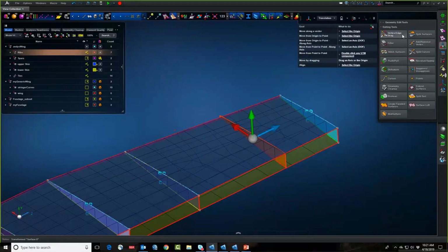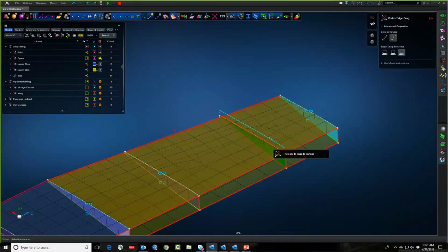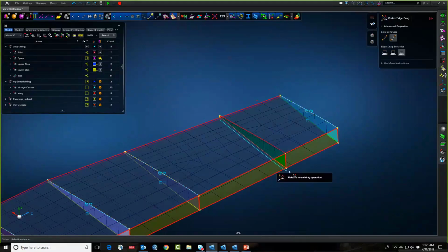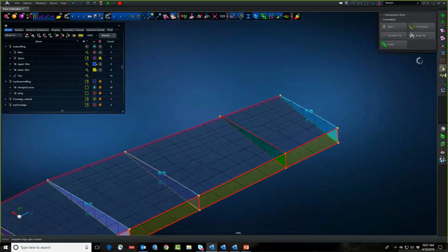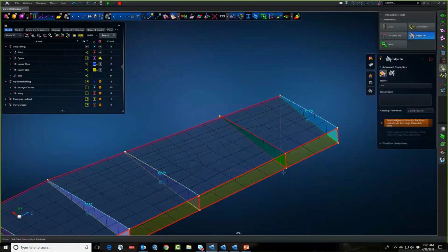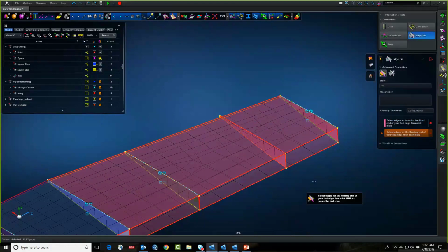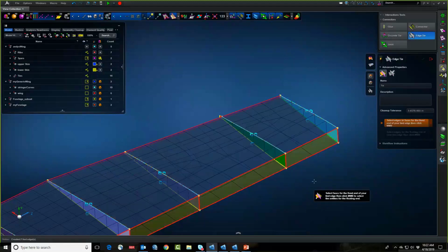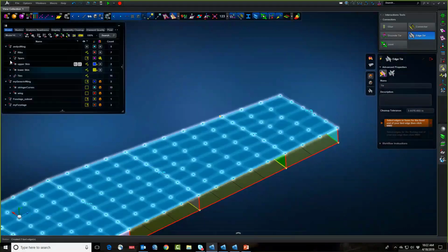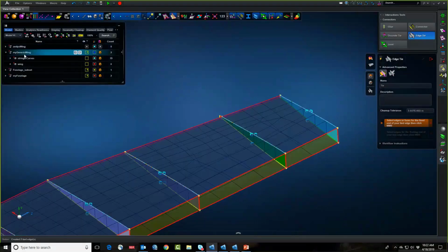Once again, remember it's direct modeling, remember it's generative, so I can just easily make sure these edges are on my surface, okay? Make sure the edges are on my surface and just simply go back to the tie and retie. Okay, and not only is this easy to do interactively, but this is actually easy to do programmatically as well, to detect this. Apex will actually let you know when things are broken. Okay, so let's go look at another example.